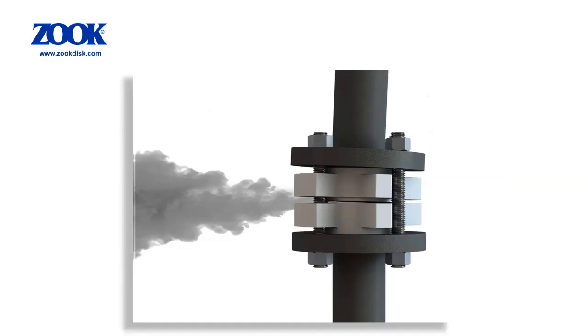Misaligning holder and disk components or incorrect torque pattern can also create leaks. Similar to any tightening process, it is important to gradually increase the torque around a flange in order to provide equal loading to the assembly. Misaligned pipe like that shown in this picture or incorrect flange torque can result in multiple leak locations across a rupture disk assembly. Some manufacturers offer pre-torque holders which allow the installer to preload the disk and create a leak-tight assembly prior to field installation.